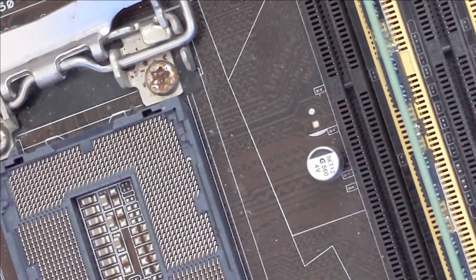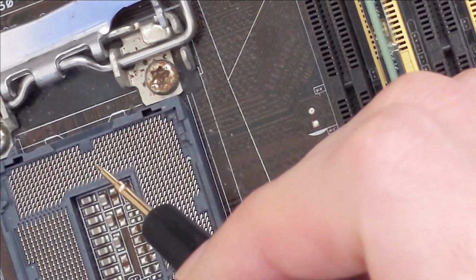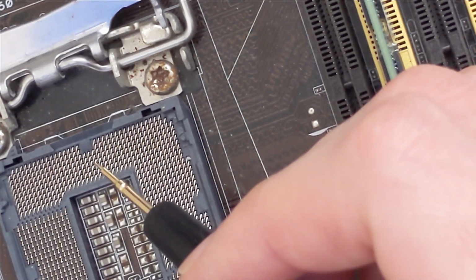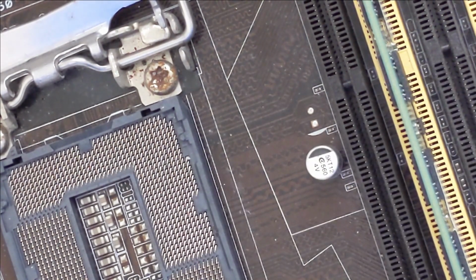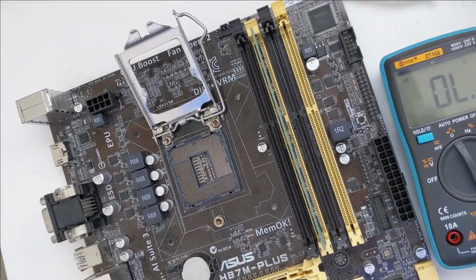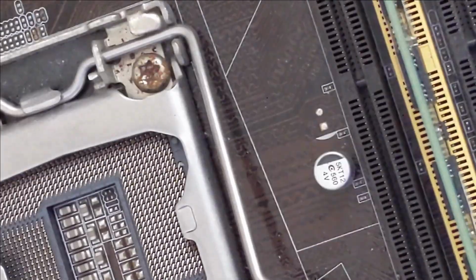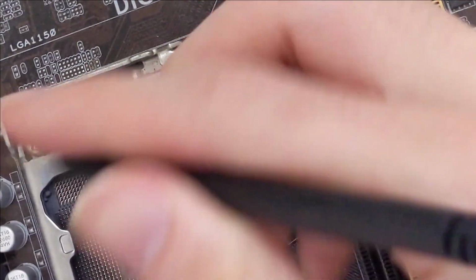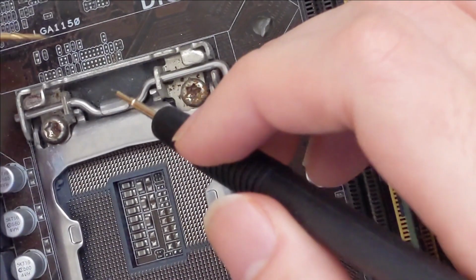Finding the CFG2 pin location of the motherboard is actually not that hard. All we need to know is we have the location of the actual CPU pin, which is this one here as shown on the board view, and we just use a multimeter in continuity mode to check which pad it actually maps to. I've actually done that already, and on the top bank of resistors you can see here that it should go to this if I probe with the multimeter correctly.